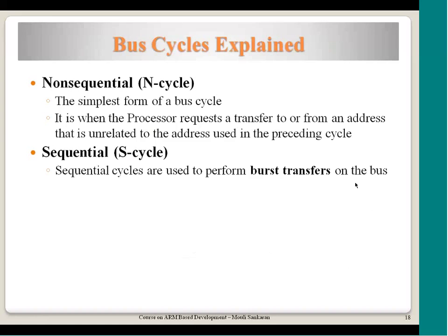Until this sequential mode changes to non-sequential or some other cycle, either an internal cycle or a coprocessor cycle, it will continue to read from the sequential addresses starting from the first address. But one thing you have to remember is that every cycle the incremented address is also put on the address bus. But memory can comfortably go and do the data access